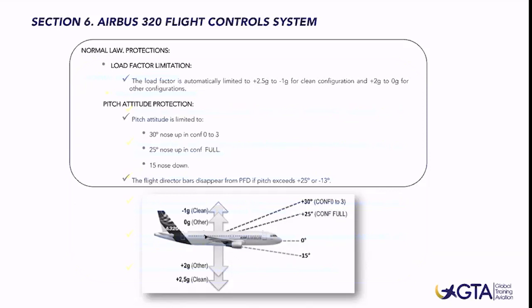And as the speed increases, the side stick nose down authority is progressively reduced, and a permanent nose up order is applied to aid recovery. So even when this high speed protection is active, even if the pilot is applying full forward side stick input, you will notice how the airplane is taking your nose up just to keep you out of this overspeed protection.